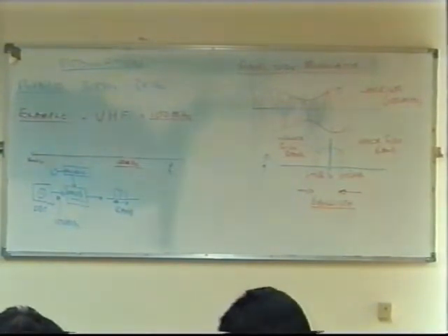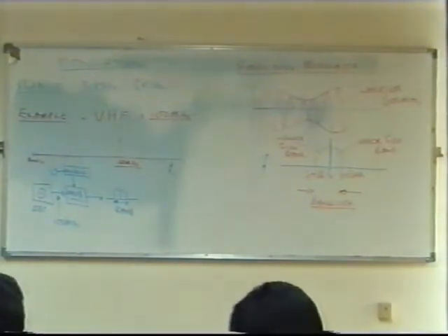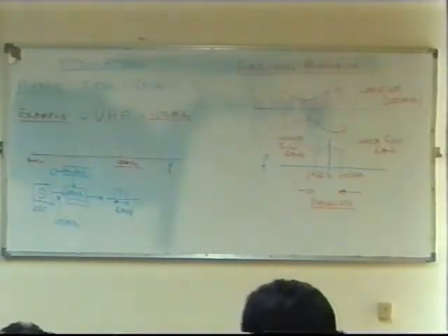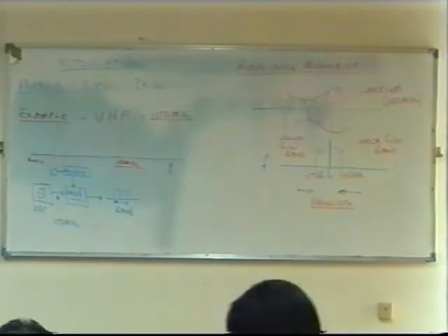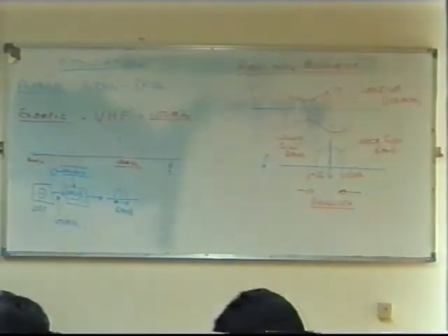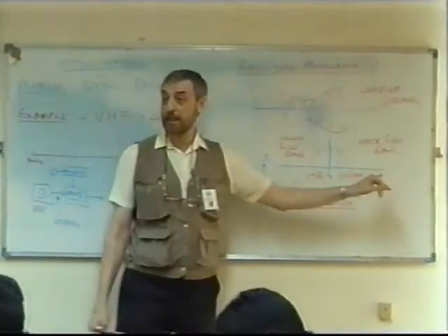The bandwidth. That's the band. What is the bandwidth then in that case? What's the bandwidth of that signal? The difference between the maximum... Six. So what is it? 6K. 6K, yes. That's right, it's the difference between the highest frequency transmitted and the lowest. In this example that I've chosen here, it would be 6K, wouldn't it?